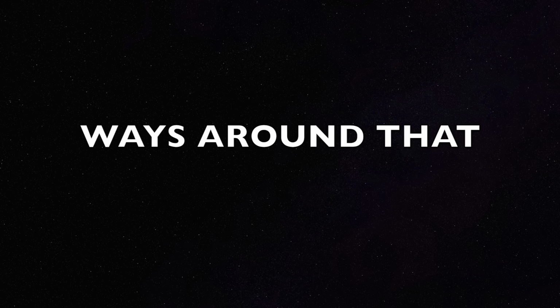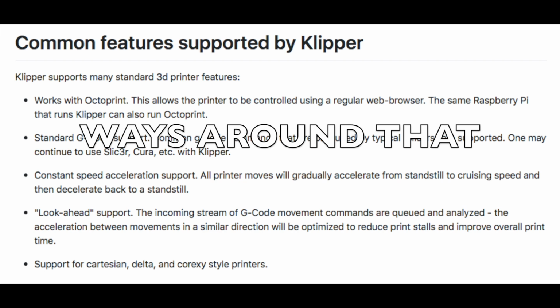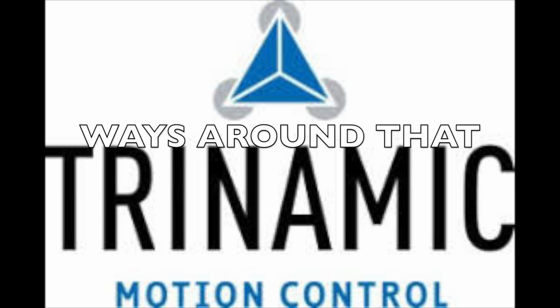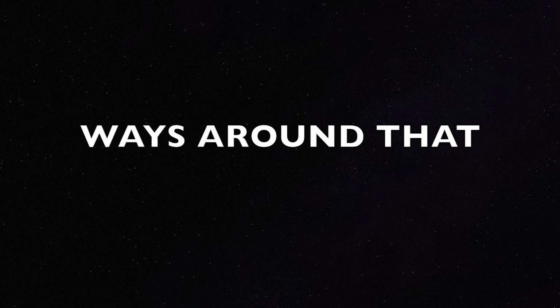episodes. One option is using, like I mentioned before, a firmware like Klipper who does the math on a 32-bit computer, and then it sends that out to your 8-bit MCU. Another option is to set your stepper drivers down to a larger step size, like instead of 16 times microstepping, you can use quarter stepping. And then if you're using a chip like a Trinamic chip who has a lookup table that lets you do 256 times interpolation, you can smooth that quarter stepping back out so it's nice and quiet, those types of things. But again, we'll get to that in other videos.